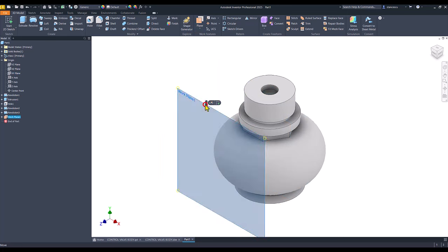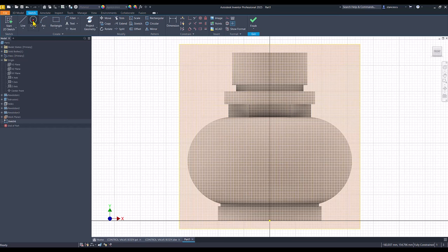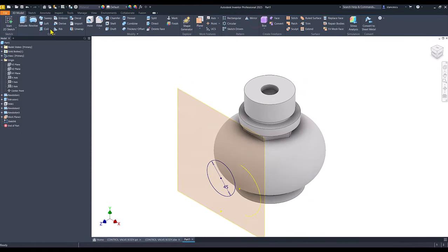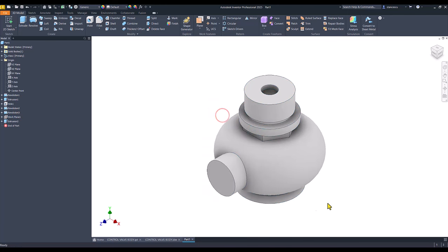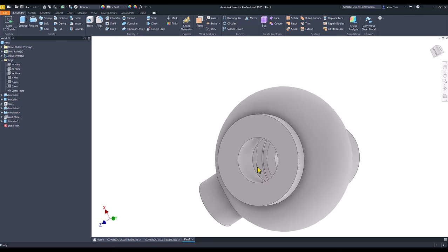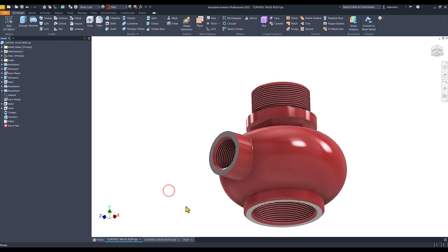Okay, we use this face, this plane for a new sketch. Diameter of 45. I project this arc to have the center, and I place on the same horizontal, X is to the right, these 2 points, and on the same vertical the other point. Finish sketch, extrude to the part. Okay. You see, I didn't go inside. Inside is as it was before.